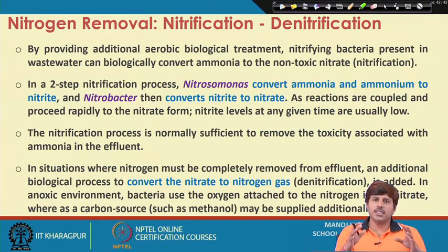However, this needs larger residence time. We need to give larger retention time if we want to achieve the nitrification process, because generally the nitrifiers are slow growers, so they grow slowly and they act slowly. So, in the conventional treatment system, the residence time that we provide is not good enough for nitrogen, so not much nitrogen removal takes place, and only the CBOD, or carbonaceous BOD, eventually gets removed in the conventional activated sludge process or those conventional aerobic treatment systems.